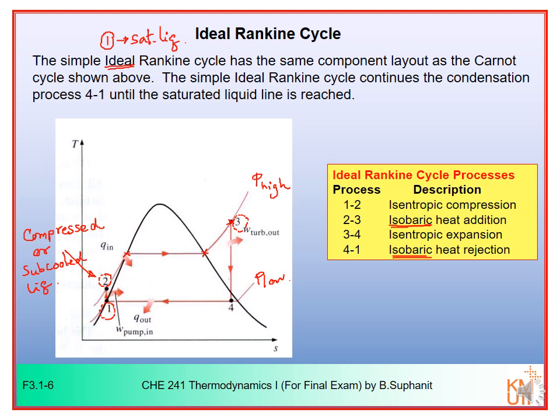The next step would be isentropic expansion. Isentropic expansion from number 3 to number 4. Okay, so the exit from the turbine, it may be in the vapor phase region or still superheated, or it may enter the two-phase region, or we have some liquid formation at number 4. It depends on the original point or the inlet point to the turbine.